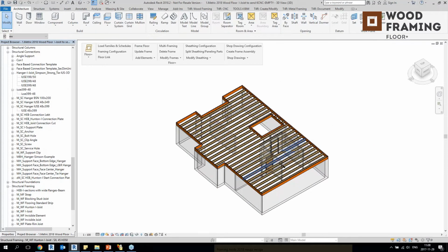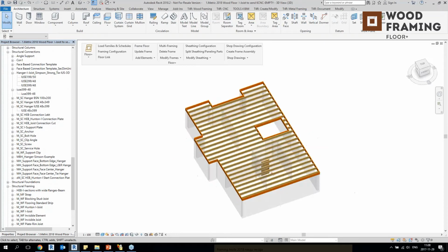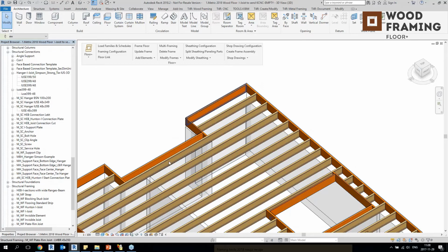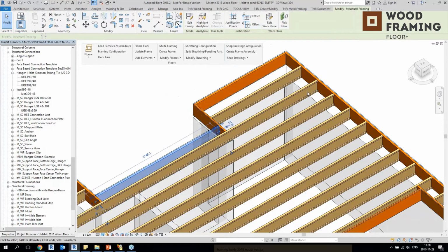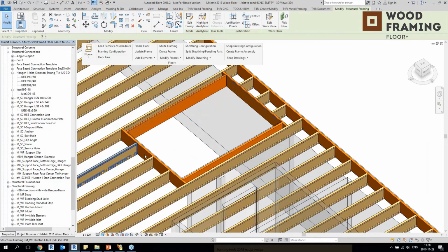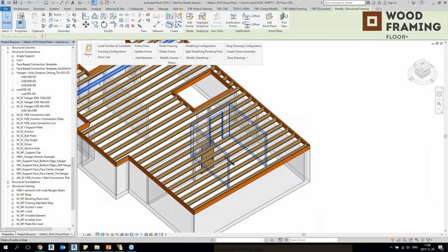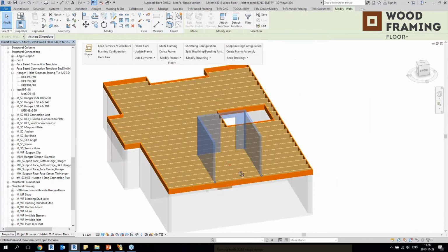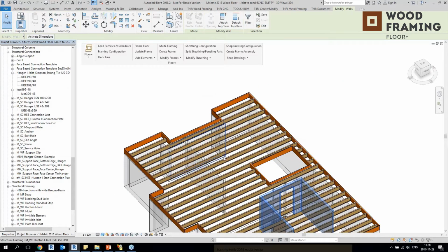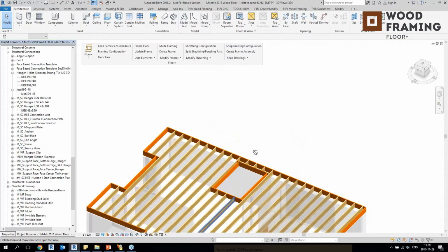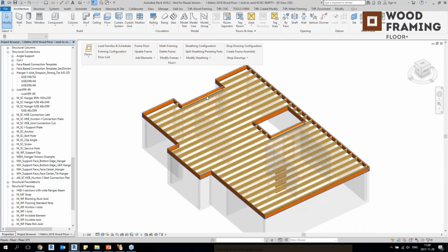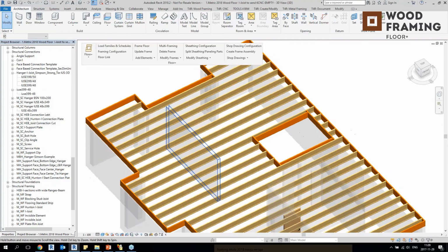Okay, I'll go to another 3D view without the exterior wall so we can see better. Yeah, you can see that my structural framing elements for the rim joists are added. Also I joist elements are added. The opening is framed, and right here you can see the bathroom walls, and I will modify this situation right here. And now we can start to modify the floor. Of course, if you don't need to modify it, you can leave it as this. This webinar is about complex situations.